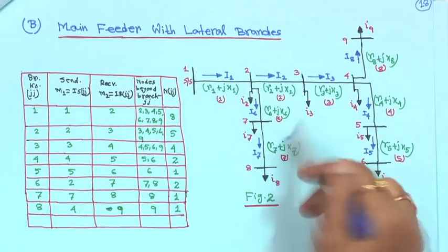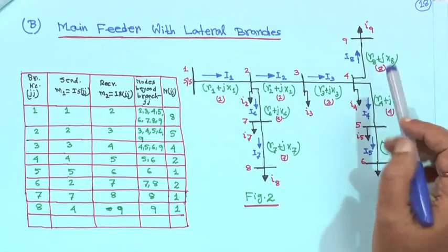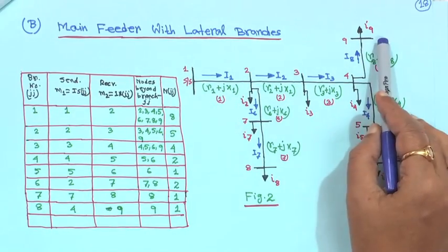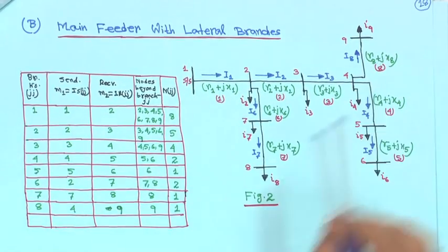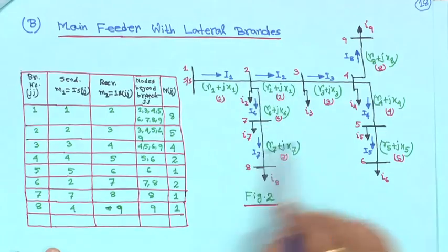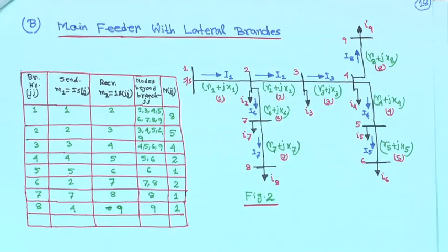So, the way you want, you can number. It is not a problem, just try to maintain that the numbers should be between 1 to 9. After that, wherever you put those numbers, it does not matter, because you have a 9 node system, right. The only thing is connectivity; according to connectivity you have to form this E matrix. The E matrix is important, right.